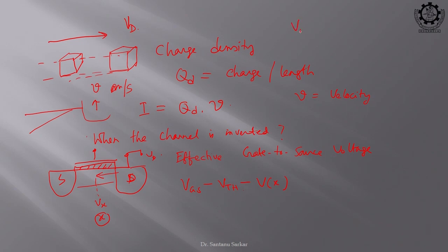Suppose your Vd is equal to just the overdrive voltage. So, the effective voltage at this point is Vov minus Vx, which is Vov minus Vov, equal to 0. So, there is no vertical field at this moment, and the channel just stops there. That is known as pinch off and channel length modulation. So, we will come to this.